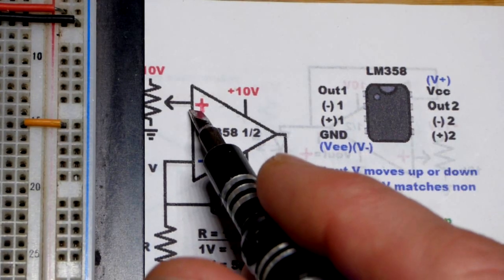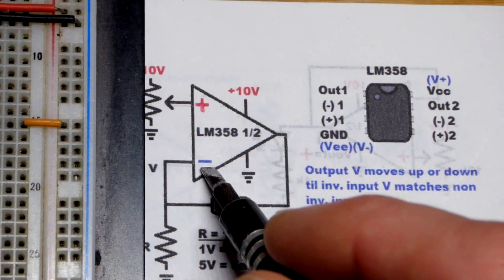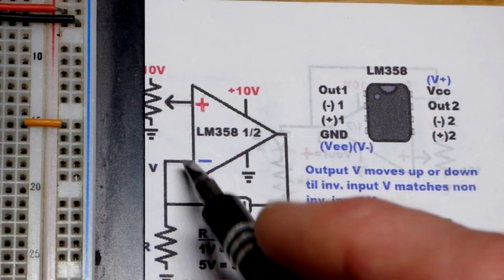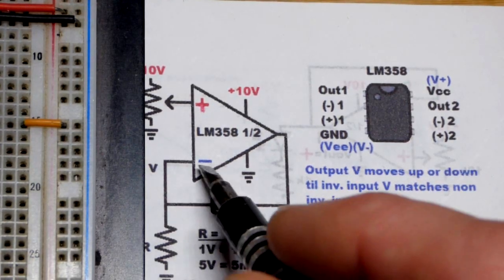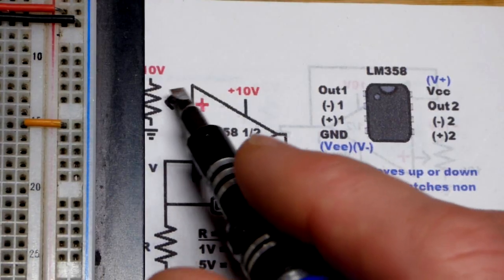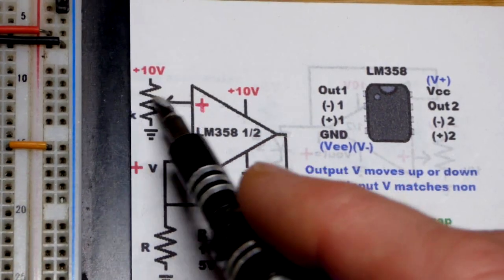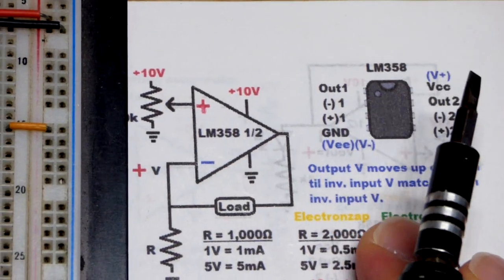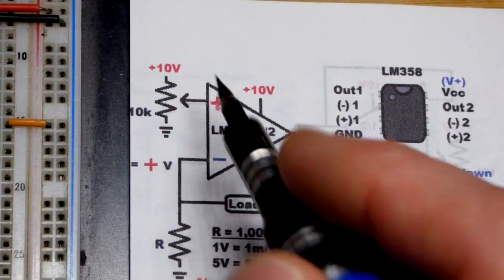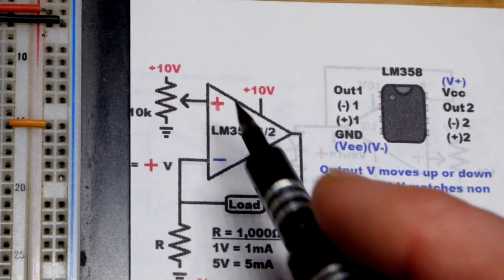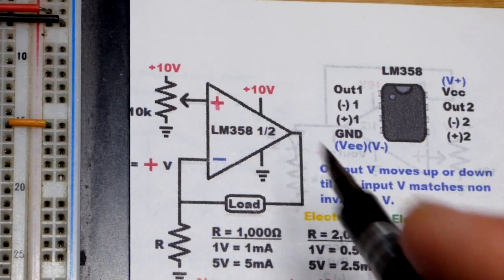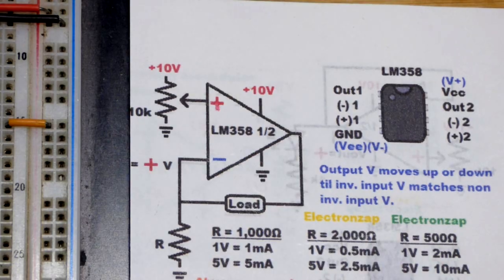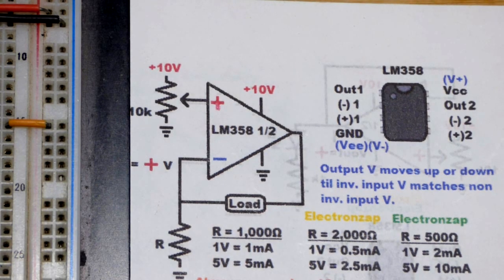I drew, though, the non-inverting above the inverting, and probably did that because we got all of this going on right there. I wanted to put it down lower, and it's headed to ground right there. Whereas the trim pot, it's not taking up much space on the drawing, so I probably wanted it up higher like that. Makes sense. It's a 10,000 ohm trim pot we're going to use later on. And so therefore I swapped the position on there. You'll see that all the time. You may even see it pointing down or pointing up. I don't know. Whatever was easiest to draw at the time. So always pay close attention to the physical pin layout versus what's on the schematic.